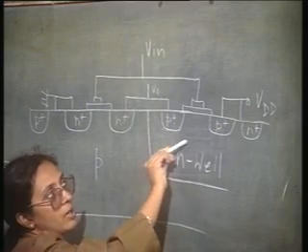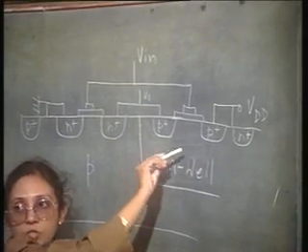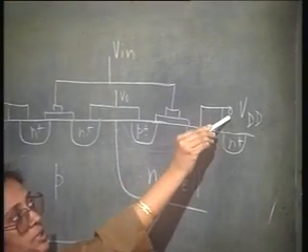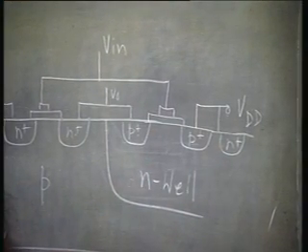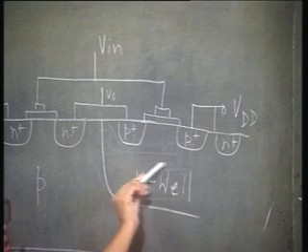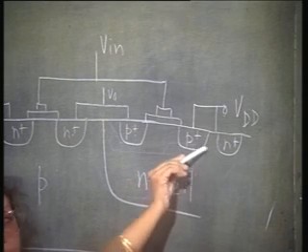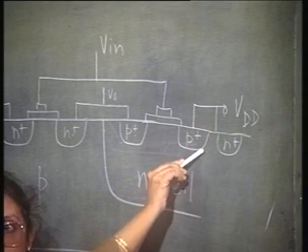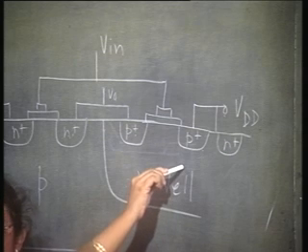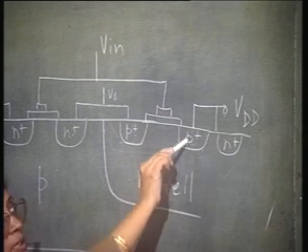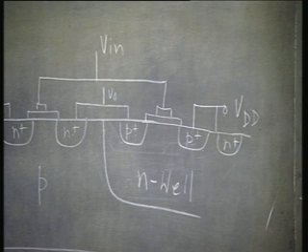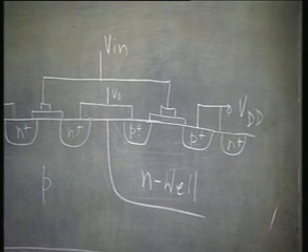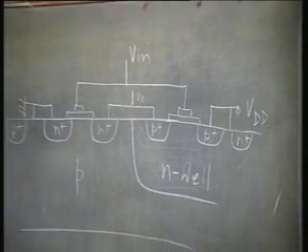In the process, we have a sufficient resistance drop here, so that, you know, this is actually connected to VDD. Between this point and this, you have a sufficient voltage drop, so that this Nwell is actually at a lower potential. That is what is making this PN forward biased. That is what is causing the regenerative problem.